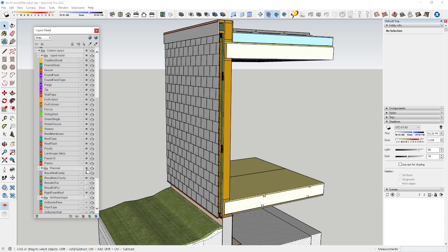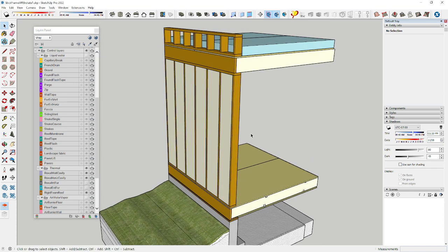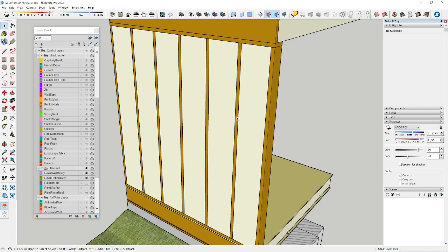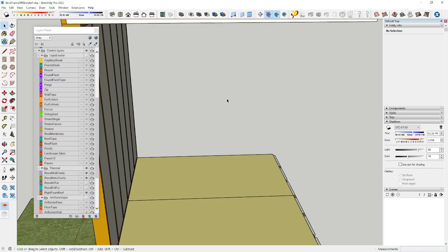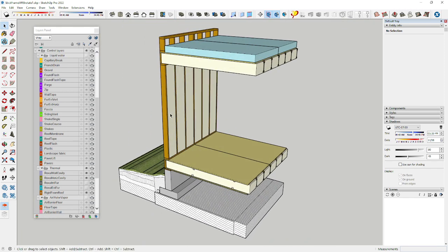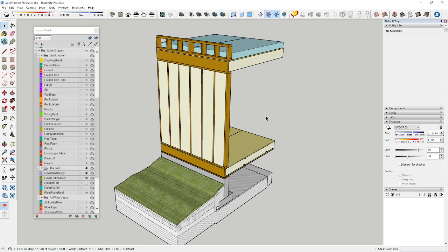If I just had a typical insulation scenario where you have studs and you have cellulose or some kind of insulation between the studs, now this stud becomes what's called a thermal bridge because it's breaking the insulation. It has less R value, less resistance to heat flow than the insulation. So it is degrading the insulation value of our insulation material by breaking it.